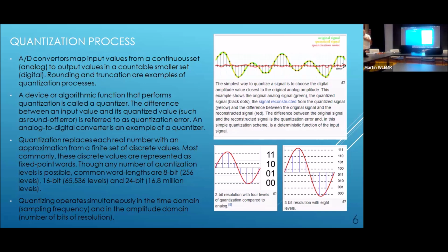And the good news is that if you have a good receiver with a decent A to D converter, that smallest possible step size is going to be quantizing noise, because you have a signal to noise ratio which is finite. And you're never really sure exactly where the signal is. Therefore, it doesn't matter as long as your step size is small enough to capture that information.